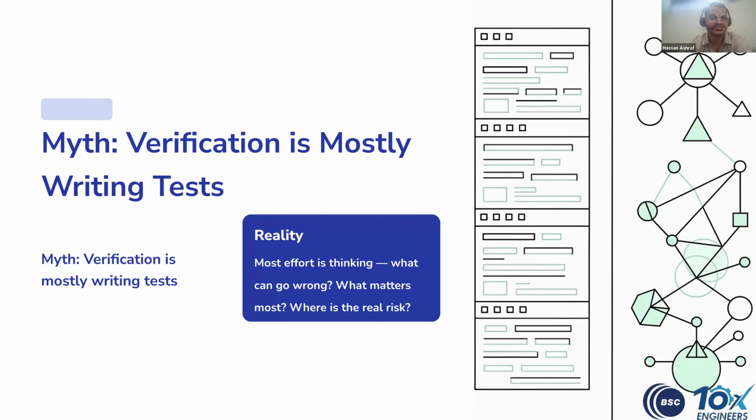We are actually limiting the scenarios that we can test, and if we over constrain something, then it is very probable that we miss some actual test case where the bug resides. If your constraints are wrong or over constrained, you'll never generate the failing scenario. Randomization is powerful, but it's not exhaustive. So you have to take a balance between CRV and direct testing.